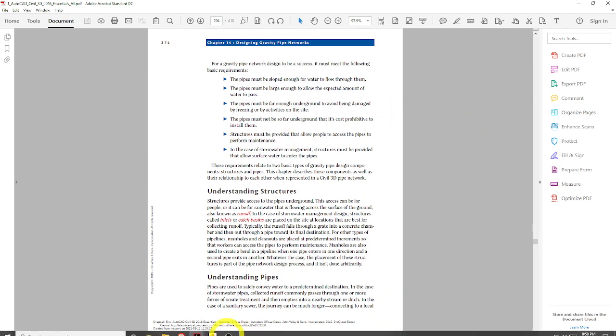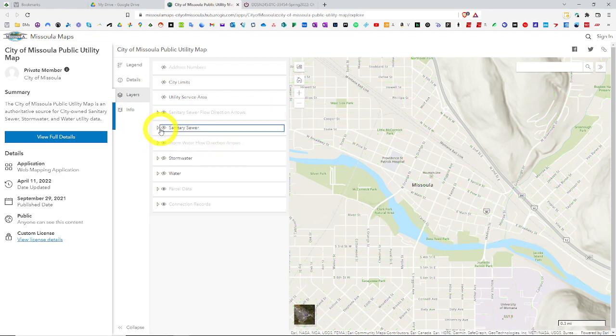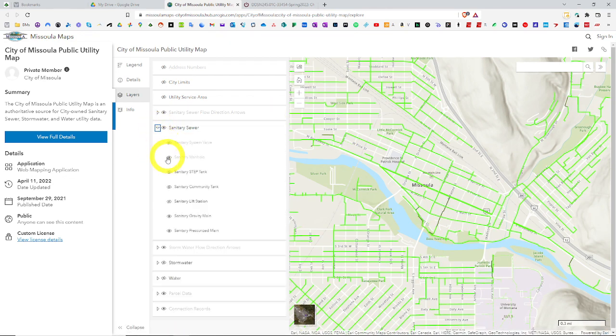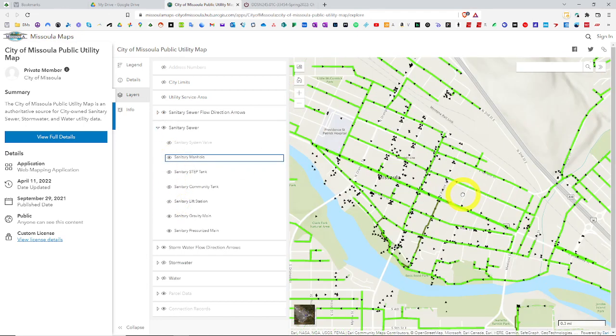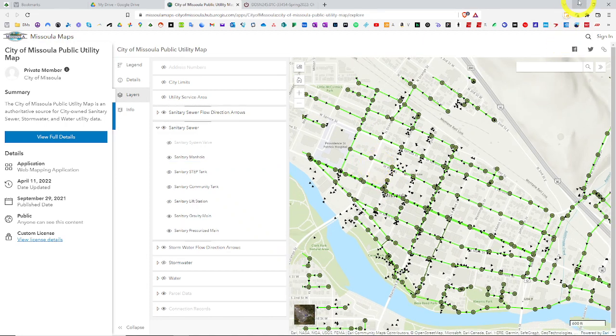Just like on this picture of the city of Missoula, for example, sewer manholes are in very strategic locations to do maintenance, to provide better design flows, and to isolate areas of the pipe network, so you have them minimum distances from each other, or at critical intersections where two pipe networks meet, perhaps. So that is a critical design feature.